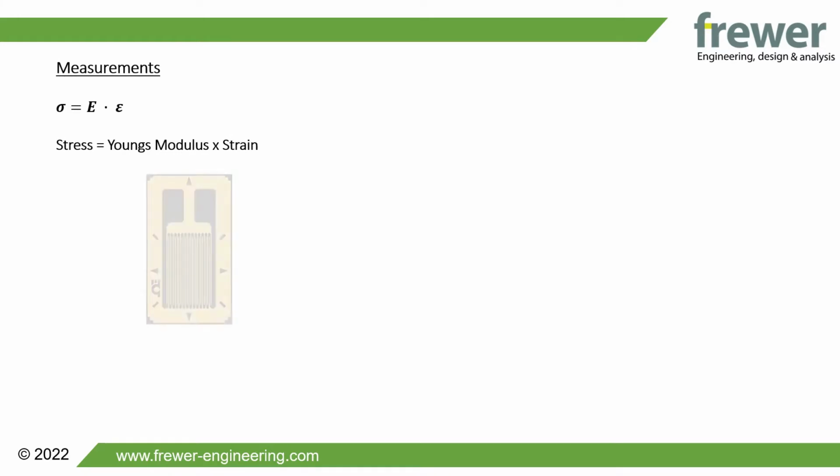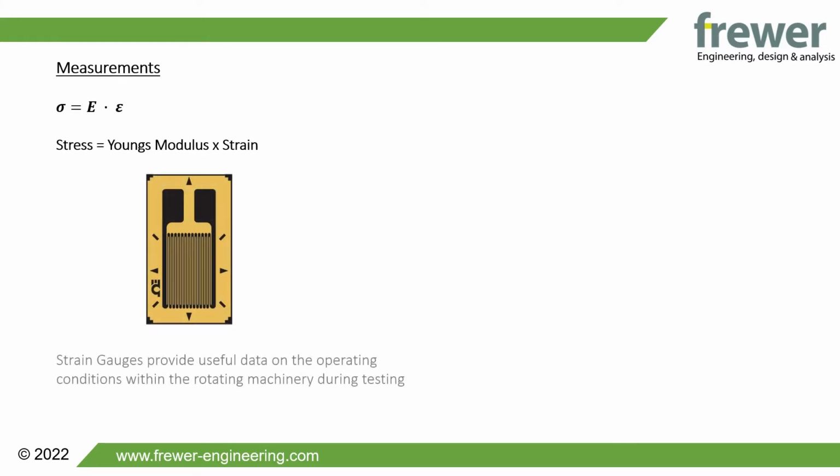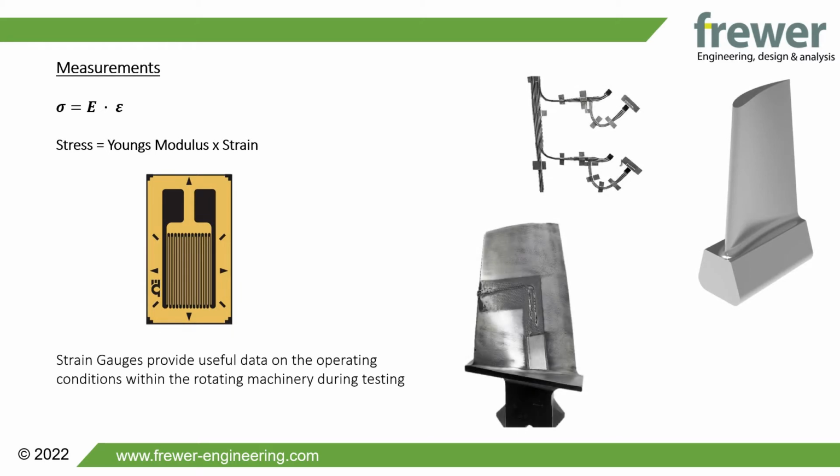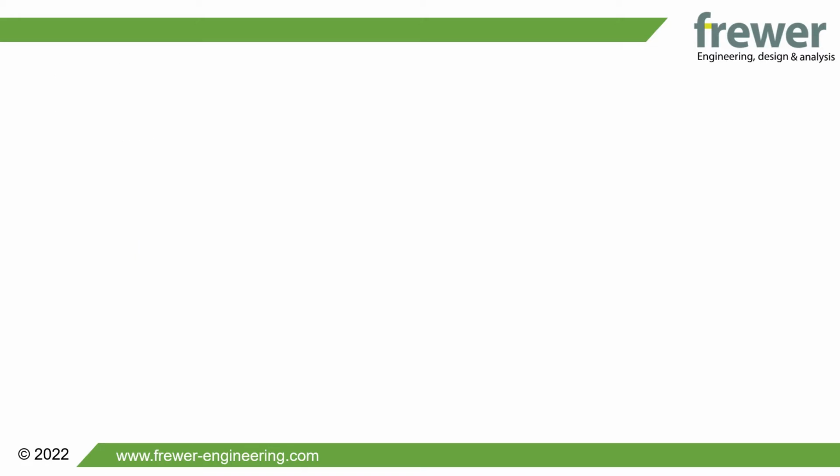During testing, blades are fitted with strain gauges at critical locations in order to measure their stress condition. If measured stresses exceed a specific value, the test is shut down. Positioning of strain gauges can be complex. The number of gauges should be minimized to help with instrumentation lead-out and to ensure the test is representative of the final product. However, it is crucial that all potential failure modes are captured with sufficient sensitivity.